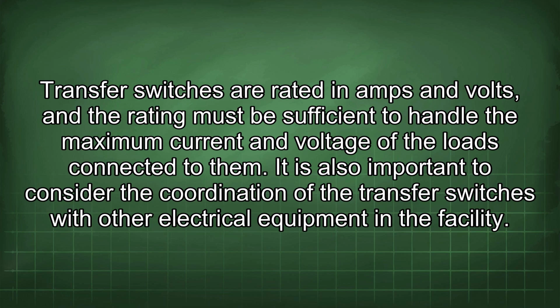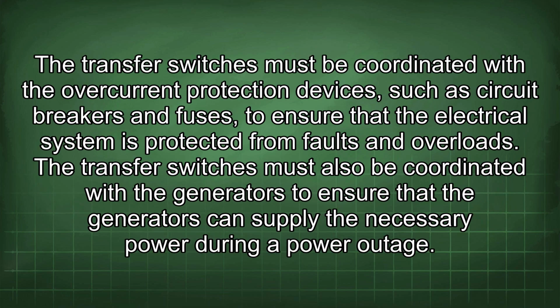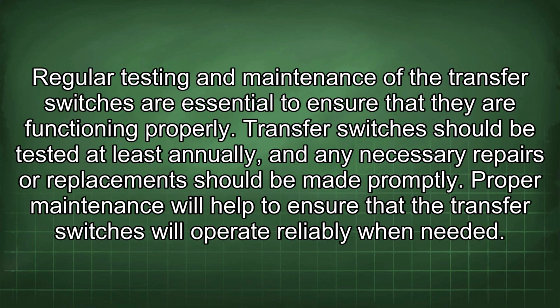It is also important to consider the coordination of the transfer switches with other electrical equipment in the facility. The transfer switches must be coordinated with the overcurrent protection devices, such as circuit breakers and fuses, to ensure that the electrical system is protected from faults and overloads. Transfer switches must also be coordinated with the generators to ensure that the generators can supply the necessary power during a power outage. Regular testing and maintenance of the transfer switches are essential to ensure that they are functioning properly.